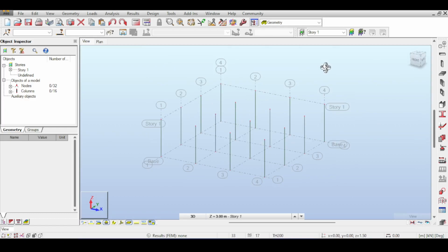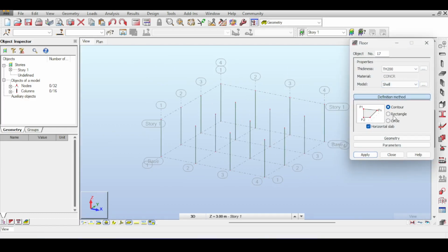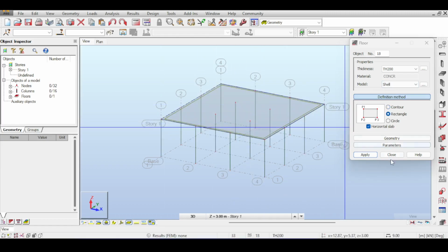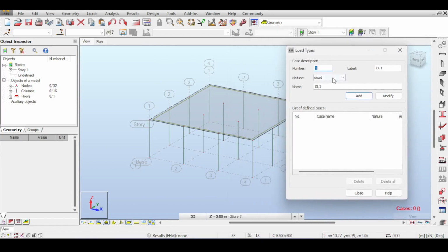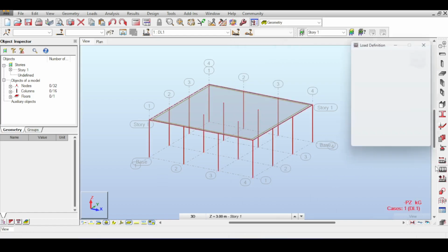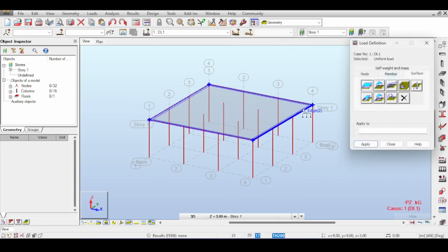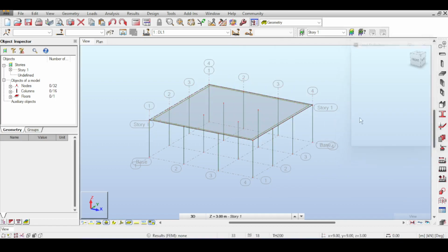I'm not going to pin anything at the bottom. And I was also going to just apply a concrete slab for the sake of analysis. It's a flat slab just for the sake of analysis. I'm not interested in the analysis of those slabs, but I'll just basically give it a slab with a force just to show some sort of force transfer. So I'm just applying 10 kilonewtons per square meter. This is just a thing.